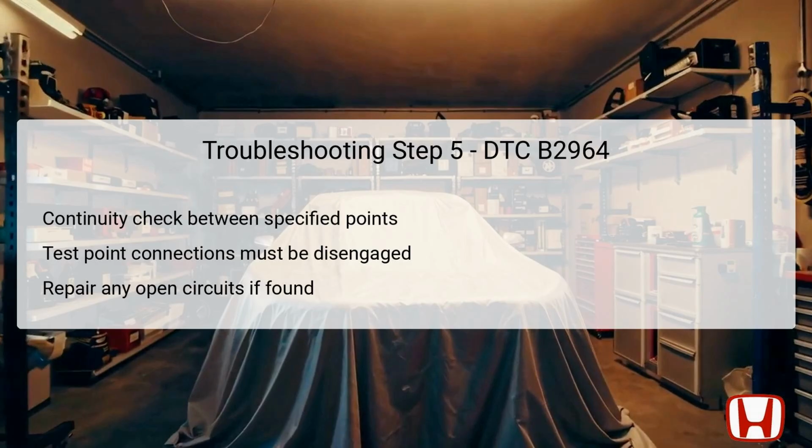Utilizing the multimeter, measure for continuity between these points. If continuity is established, the bus data wire is intact, and this suggests progressing with the diagnostic process. If a lack of continuity is identified, it indicates an open circuit that requires repair, which may involve inspecting the wiring for any damage, corrosion, or disconnections along that pathway.